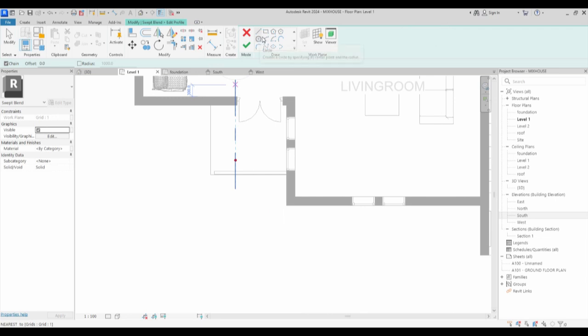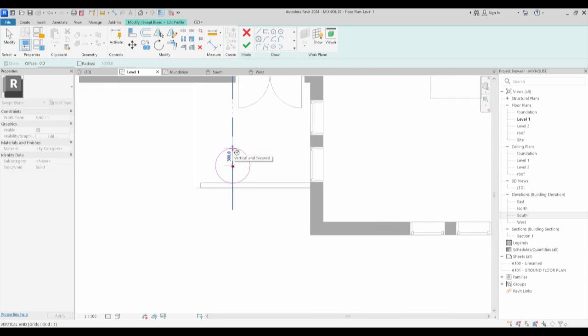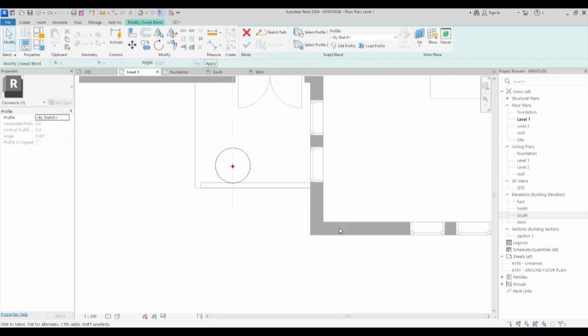So here you select a polygon or select square at this side. You can blend many things together. You can decide to draw any kind of design. So make sure you play with all these things you are seeing here, all these lines. It will quickly help you to grab what you need. So I'm selecting this one 300, that is 600 diameter. So you go back there and you say finish.